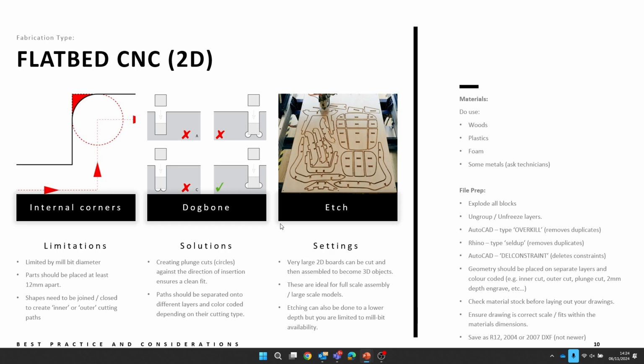Now, last thing to mention with CNCs, you can also etch as well. It's not just a case of cutting. You can etch text, you can do all sorts of engraving. You can add different bits onto it as well. They're not just rounded cylindrical pieces. You can also do 45-degree angle pieces. So you can do mitre jointed components and stuff like that. It's great stuff.